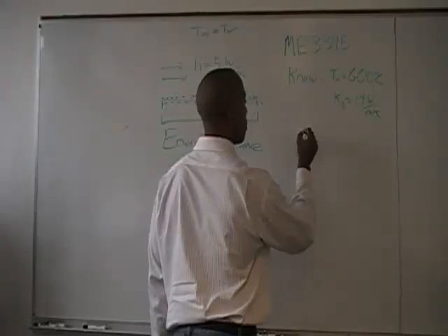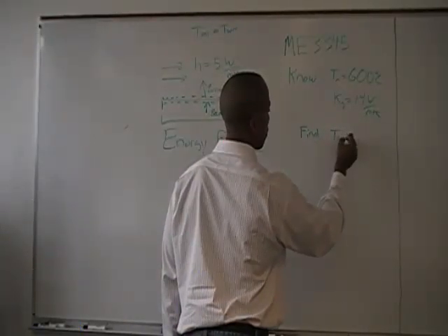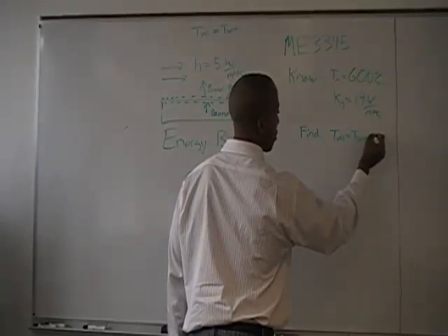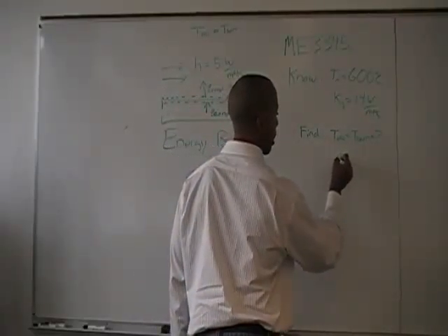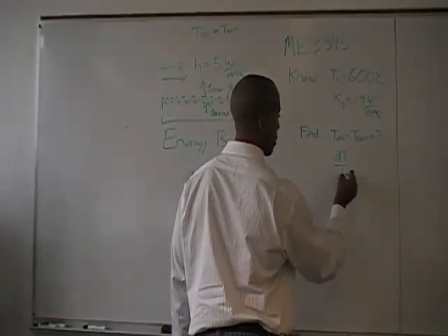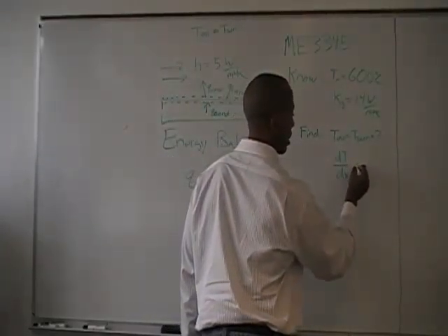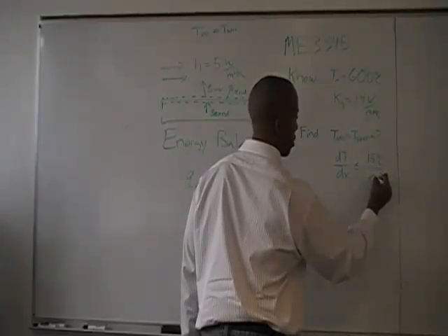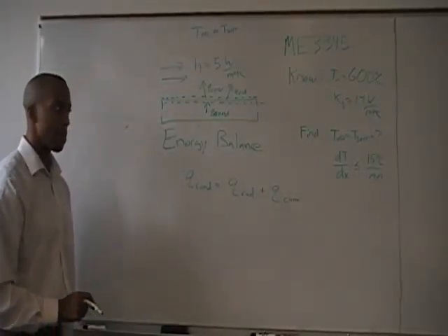So we want to find the temperature ambient, which is the same as the surrounding temperature. We want to find these temperatures that satisfy the criteria that the change in temperature with position x in our glass is less than or equal to 15 degrees Celsius per millimeter of glass material. Right?